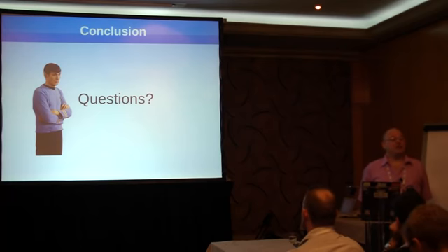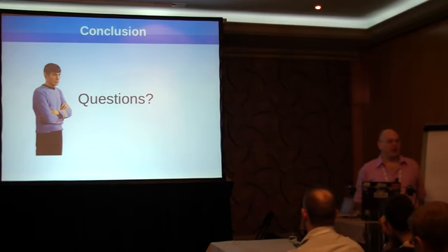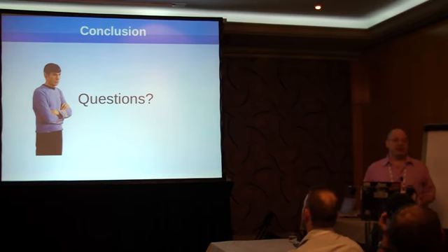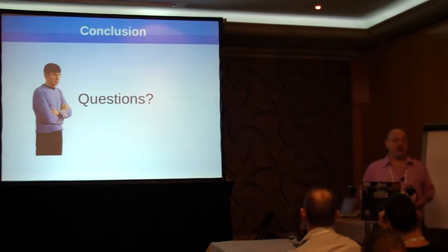When you're doing a board bring-up, you don't need to introduce more trouble than you're trying to fix to start with. Although it works well in a production environment and planning larger systems, for my cases, board bring up, I try to keep things extremely simple: one master, and usually I don't put more than 4 slave devices on one bus at a time.